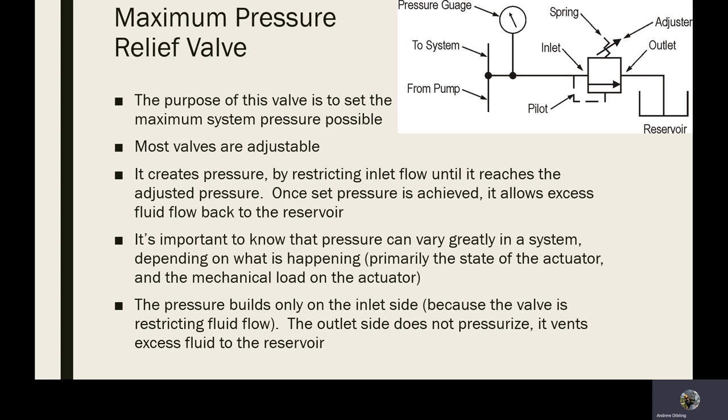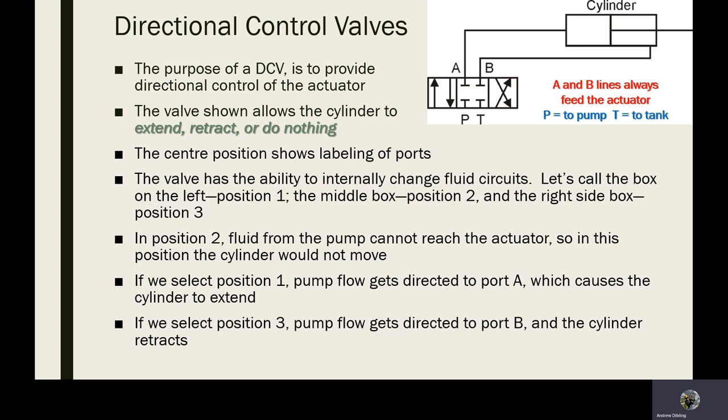If you need to adjust the pressure, we'll get into that. There are valves designed to do that, that will use that pressure and regenerate it back into the circuit softer or divert it, but they won't hammer on, hammer off, which is exactly what a maximum pressure relief valve does. Water hammer was the term that we use for that, and it's very hard on components.